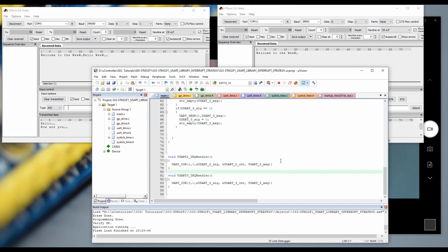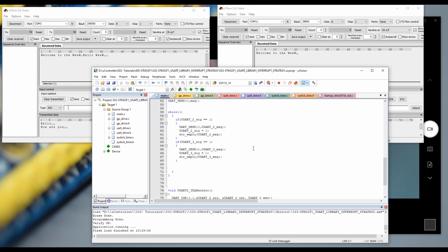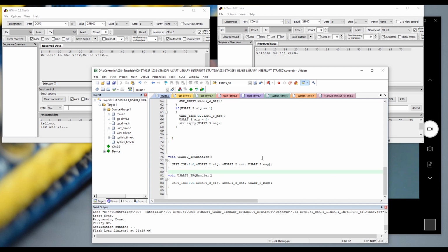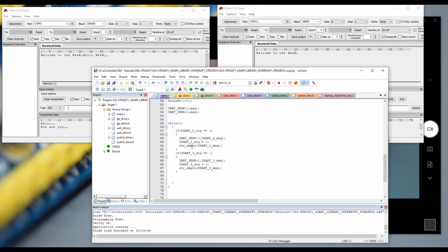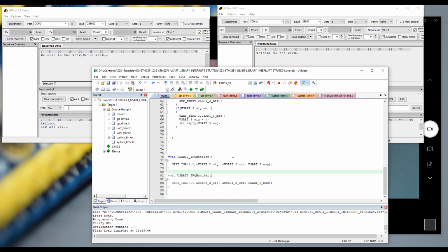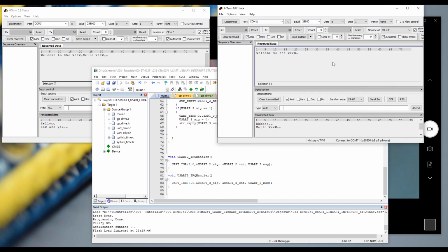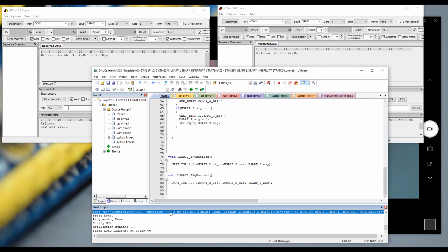So you can see, even with a different baud rate, you can now use the interrupt without really impacting your mainstream. Within this function, you just give a signal to the mainstream to do some job, and even the reception, even if you are sending a very long sentence, it will not affect the performance of your PC. Let me take a very long sentence, for example.